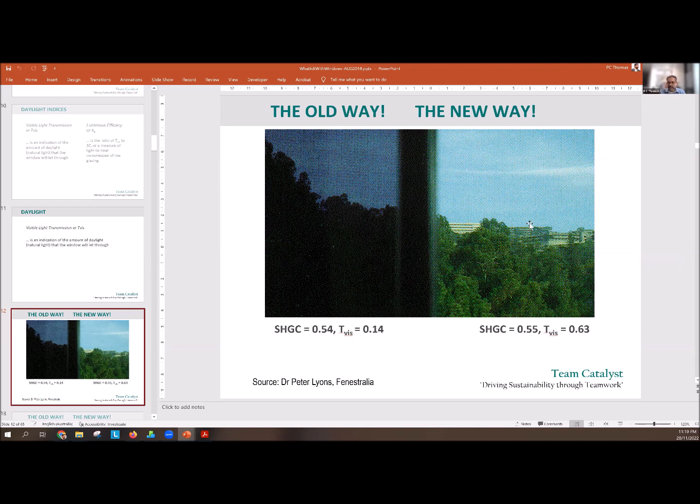How do you decide what is little or not? That's when all the daylighting calculations come in. In Design Builder, you have Radiance built in, and you can do daylighting calculations with that. If you remember, Yashima was talking about glare. So there are 2 or 3 different kinds of daylighting calculations built into Design Builder.